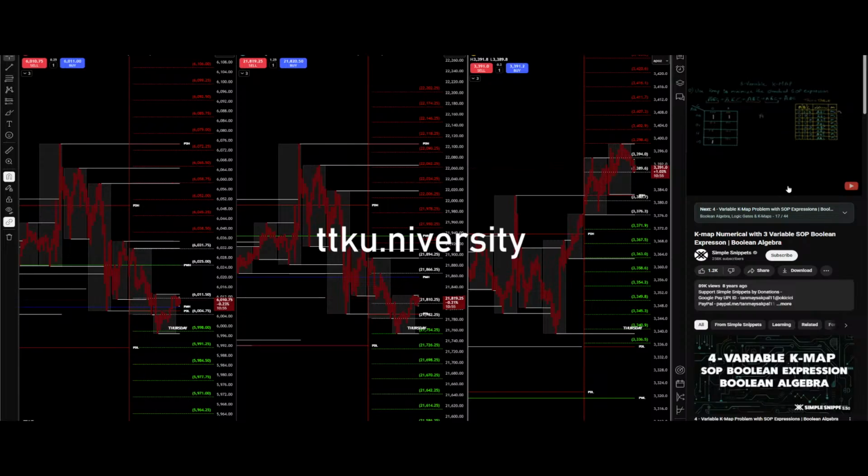For this term, A, B complement, C, we are looking at a cell value which is 1, 0, 1. So that would be this cell value. And for the last term, that is A complement, B, C, we are looking at cell value 0, 1, 1. So that would be this one. Using the truth table and the binary values, I have mapped this entire expression to the K-map format. So wherever I have written a 1, it corresponds to a product term or this term. Now we are done with the mapping.